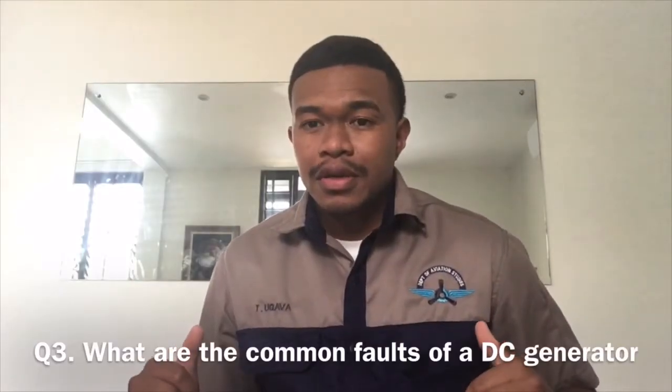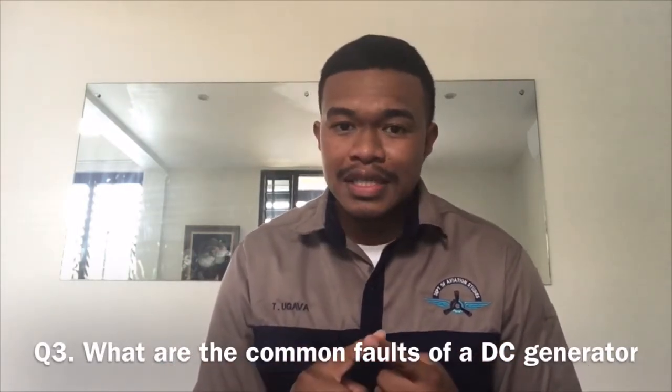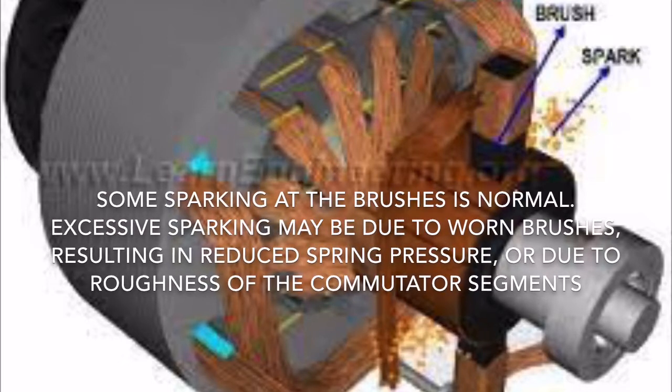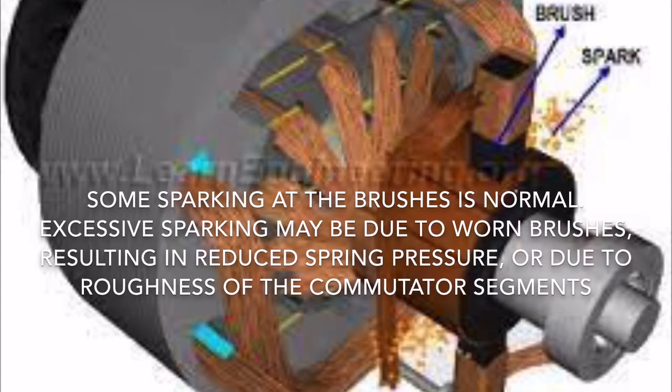Question number 3. What are the common faults of a DC generator? We got 1. Sparking of brushes. Some sparking at brushes is normal. Excessive sparking may be due to worn brushes, resulting in reduced spring pressure, or due to roughness of the commutator segments.